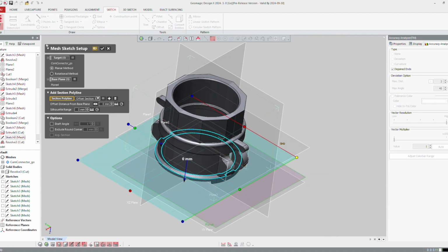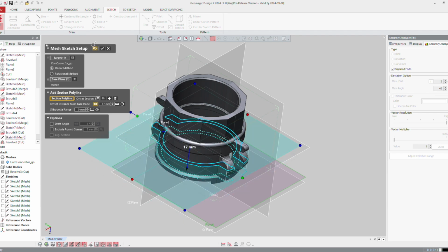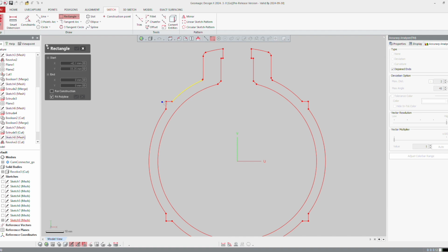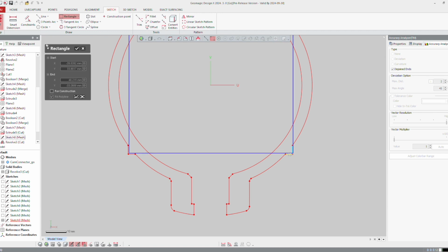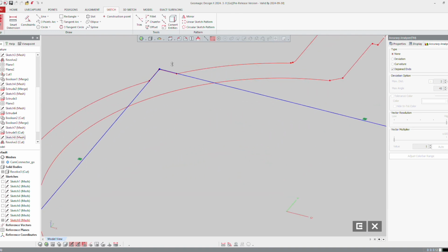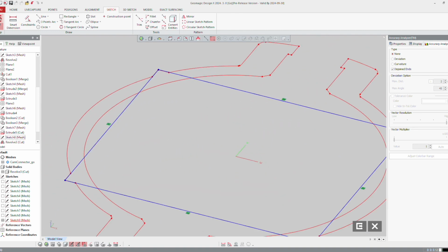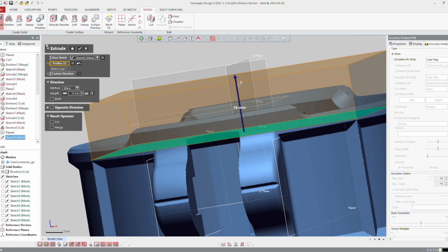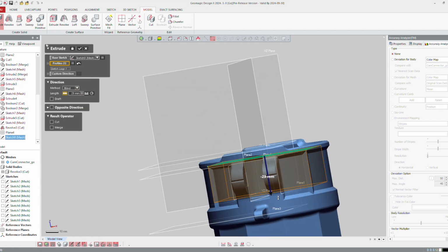Still the same process, make a big one and go inside the part. So inside the part, you can see that this looks like a square. So I will make here a rectangle, here, there, and it will fit automatically a rectangle on the selection and the last two here. And okay, this rectangle, I can create a little fillet at the end if I want to. Otherwise, I can just exit, right mouse click, extrude, and I will extrude it from here up to there.